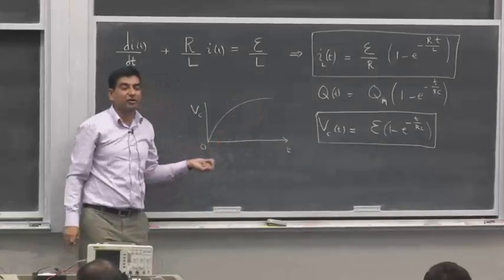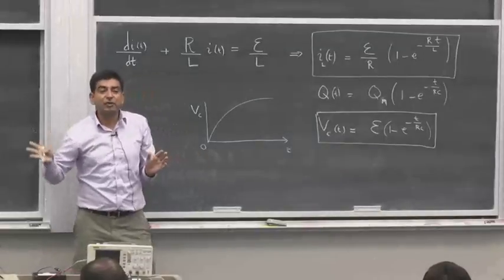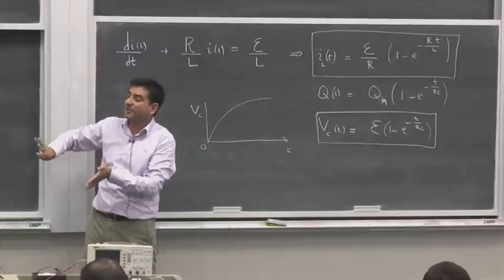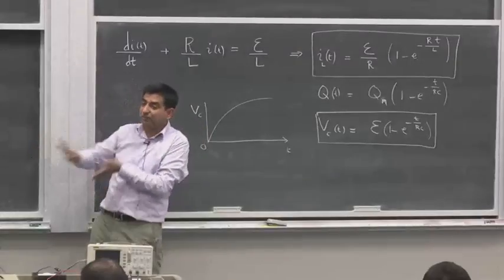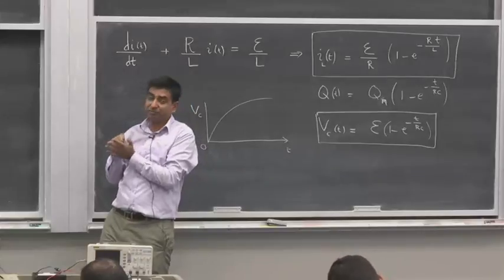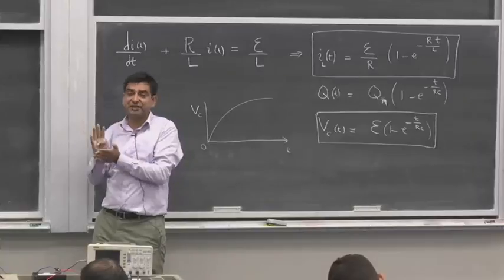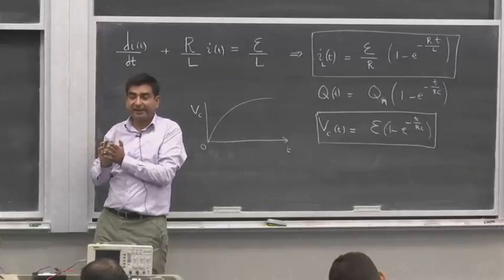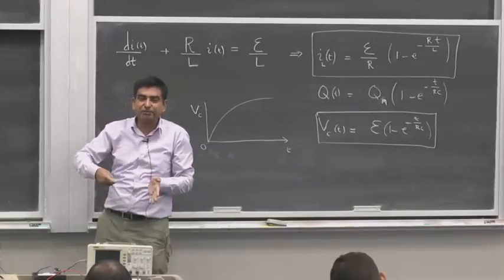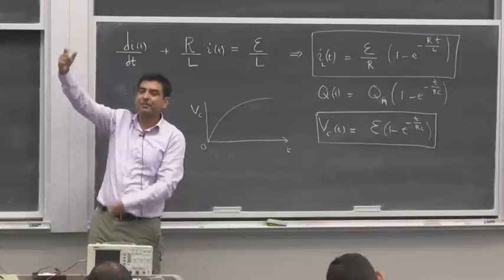Initially, the voltage across the capacitor is 0, but the capacitor cannot suddenly pick up voltage. The voltage is gradually building up inside a capacitor. So the voltage response of a capacitor is sluggish. It opposes changes in voltages, in other words. It doesn't want its voltage to increase instantaneously. There are no rapid changes in voltage across a capacitor. It's like a voltage opposer. The voltage is trying to pull it up to a certain level, but the capacitor is lagging behind in its response.